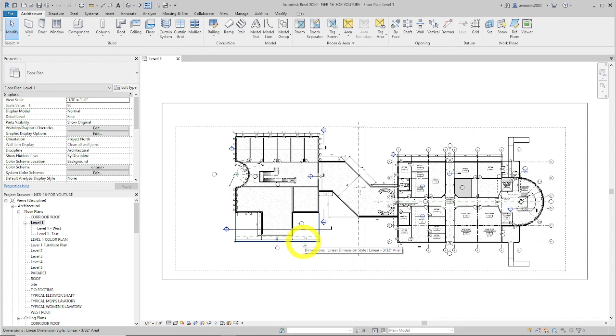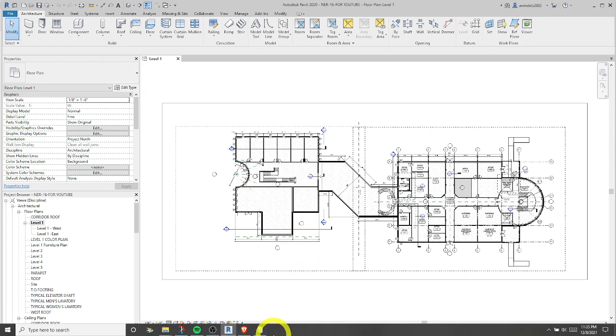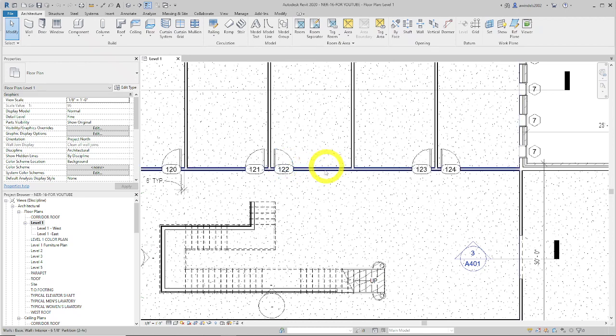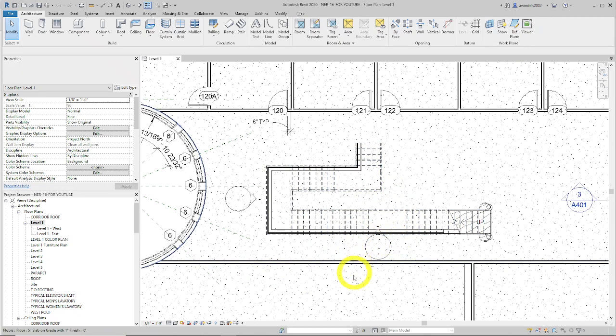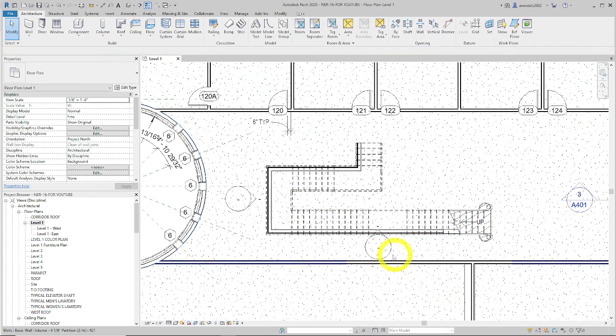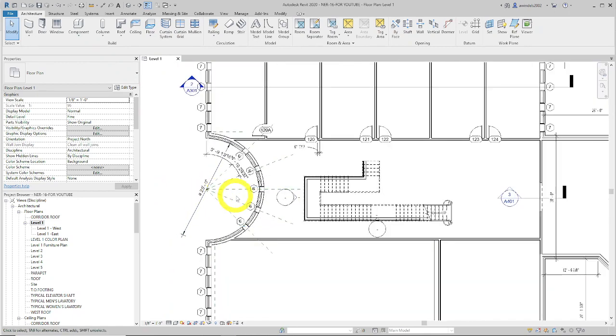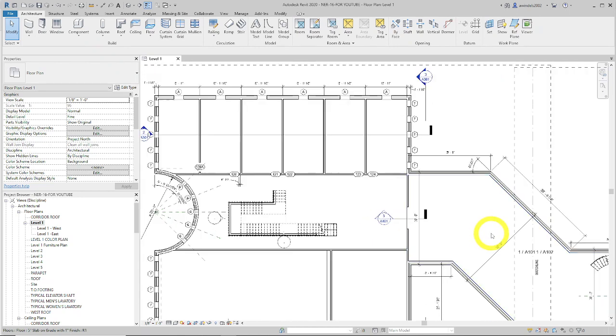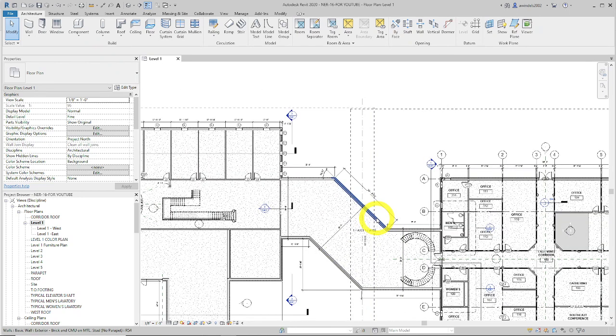So in general, a Revit model is full of databases amongst other things. So creating things like schedules, they're very common in plan sets. Populating any entity you see in here, whether it be doors, walls, stairs, floors, elevation views, windows, openings, components of any type. They get populated deep in Revit into a database. So your Revit project is basically a database for stuff like this.